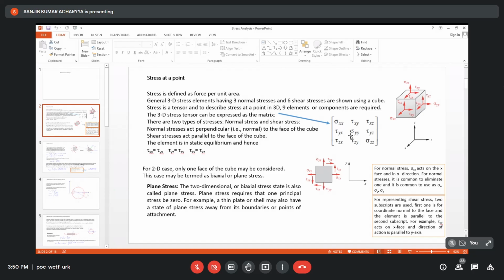Yes, sir. And what is available in material science? Material science says that, okay, in this particular grade of material, if the value of normal stress exceeds this value, you can assume that failure will occur. This is the information. Therefore, it is the responsibility of the designer to evaluate the equivalent normal stress. Otherwise, he cannot get the answer whether there will be failure or not. So now, combining all the stress components present in the material, you have to find out some equivalent normal stress. Do you agree or not?